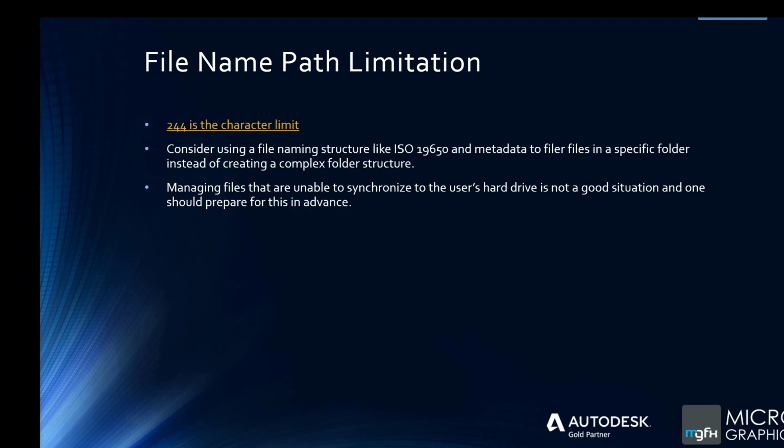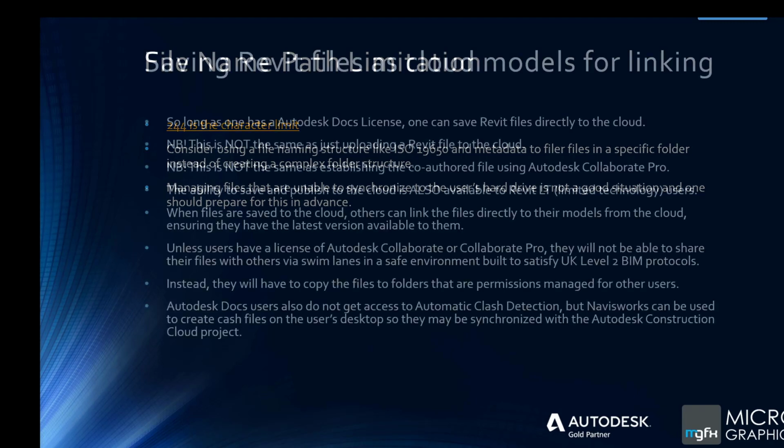36 hours, it's then going to want to check for the new files and start synchronizing. And if you just had to open your Civil 3D file and you've got a lot of those coming in, it might take quite a while for that file to load. So when it comes to extremely large sets of information like point clouds, still recommend that you keep that on your hard drive as opposed to the Autodesk Construction Cloud directly.